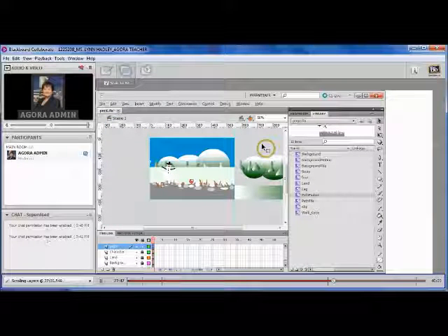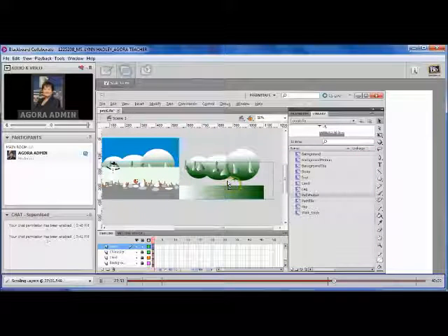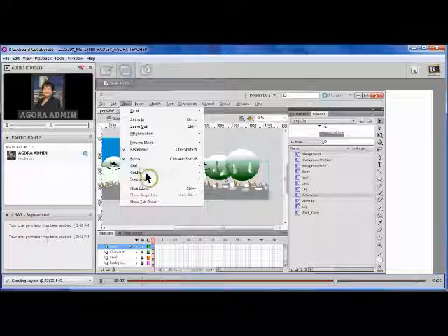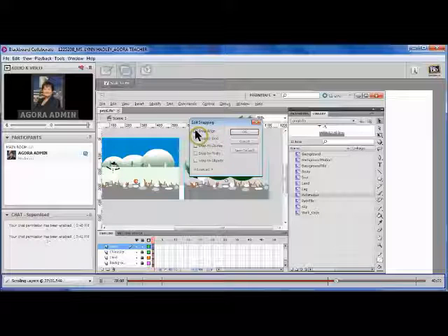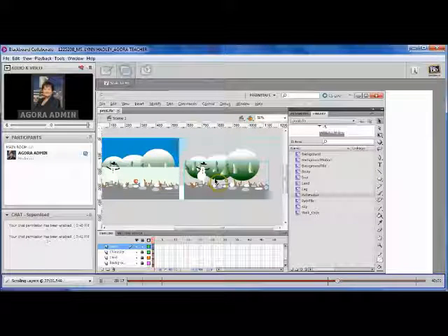So now we're going to drag and drop the other instance on here. So we're going to combine these to make them into a tile. So now we're going to have to change our snapping settings. Because we're finished drawing, we have to click Snap Align and Snap to Guides. And that'll help us in lining up our two sections here. So we just drag it out. And we carefully make sure that they come together. We want to see those dotted lines on the top and between them.